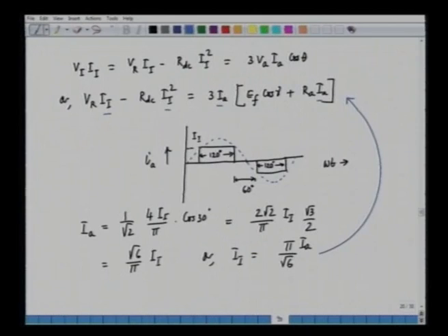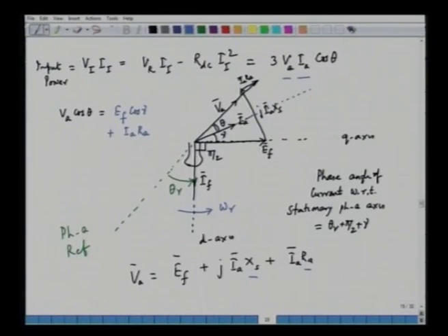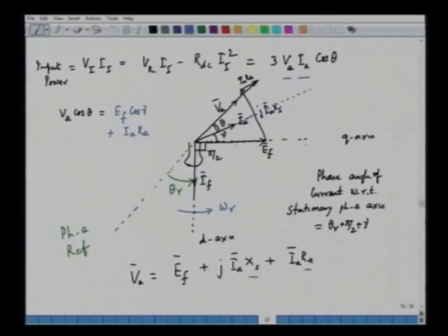And if we want to maximize this torque, we make gamma equal to 0. We know that we have a freedom here because we have a CSI, and in the CSI we can have any phase angle, and gamma in a special case can be equal to 0. So if we keep gamma equal to 0, the torque is maximized, and that is something like the torque of a DC machine, because the current is only in the q axis and the field is in the d axis, because gamma is equal to 0 and the torque is maximized.